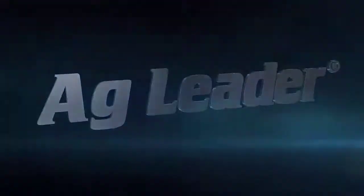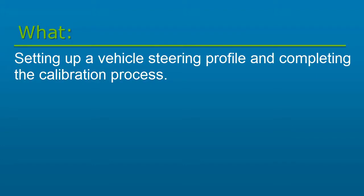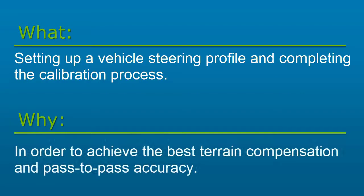In this video, we will cover setting up a vehicle steering profile by entering the vehicle measurements and ECU orientation, and then completing the calibration process to allow the system to steer the vehicle accurately. It is critical that measurements and orientations be entered correctly and that the calibration is performed in order to achieve the best terrain compensation and pass-to-pass accuracy.